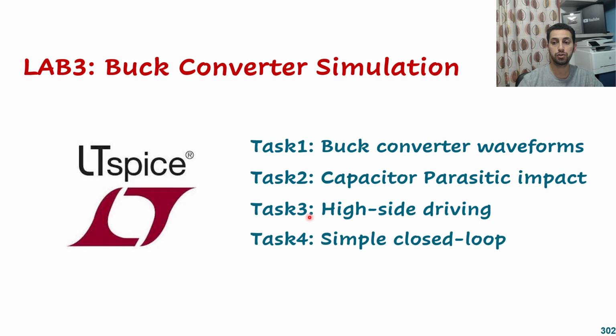And then we are going to build on all of these. Now we have the buck converter and the high side driver, and we are going to add a closed loop system. We will implement a very simple system using a comparator to decide if the output is really what we want, and to change the controller. I will go through on-off control and then hysteresis control, and then we'll implement a simple P controller, and leave the other advanced controllers for you to implement if you want.